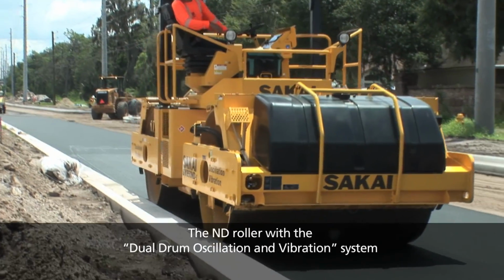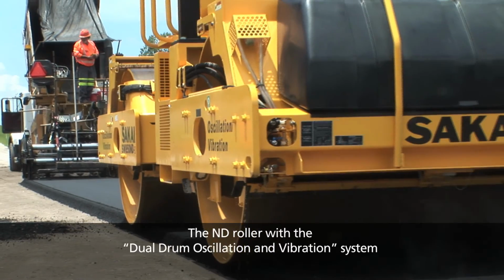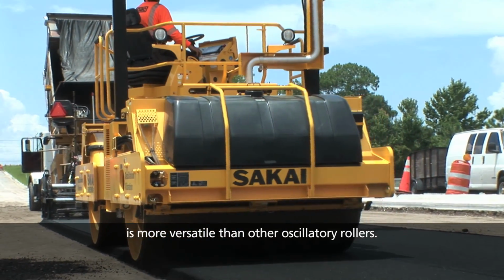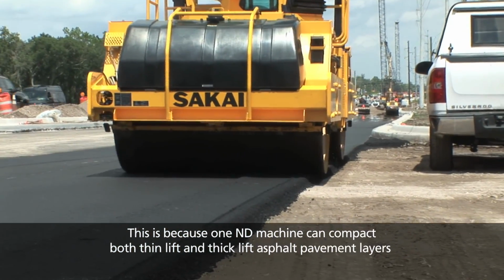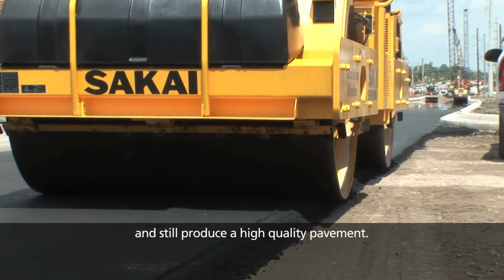The ND roller, with a dual drum oscillation and vibration system, is more versatile than other oscillatory rollers. This is because one ND machine can compact both thin lift and thick lift asphalt pavement layers, and still produce a high-quality pavement.